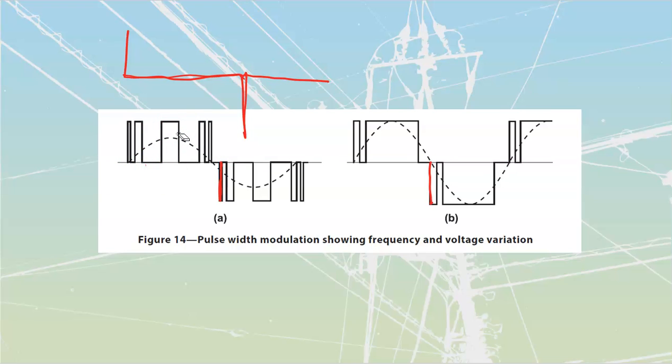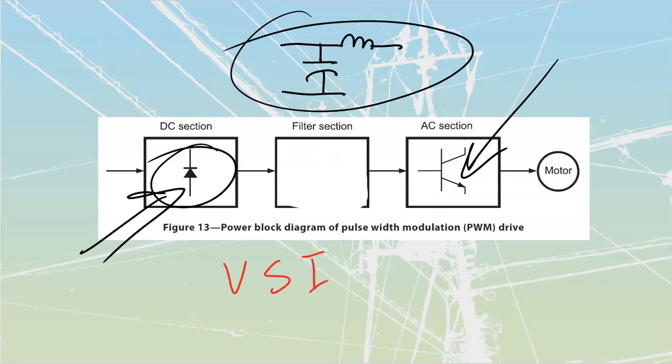Now, it's a real jerky, bang, bang, back and forth like that. But that's fine. We're not that concerned about it because we do have, once again, the filtering action of our motor coils, as well as the filtering action of our small set of inductors inside of the filter section, right? Because we're going to be stuffing that back through there as well.